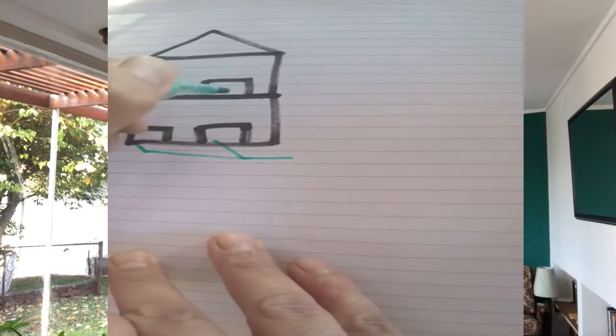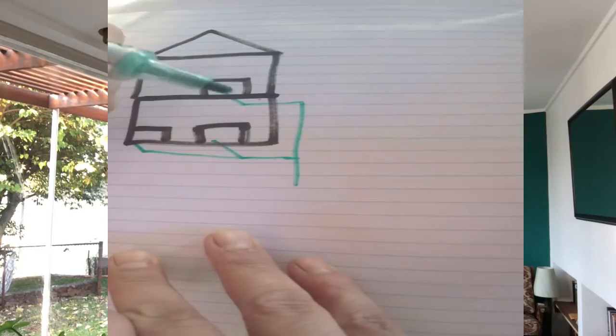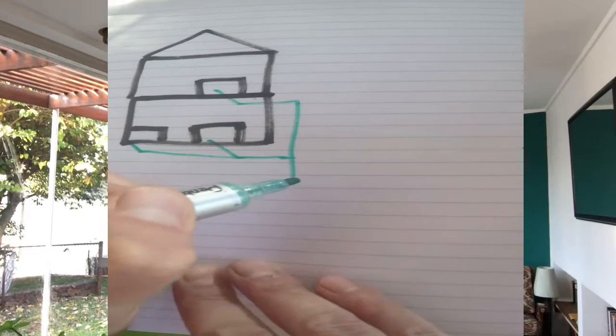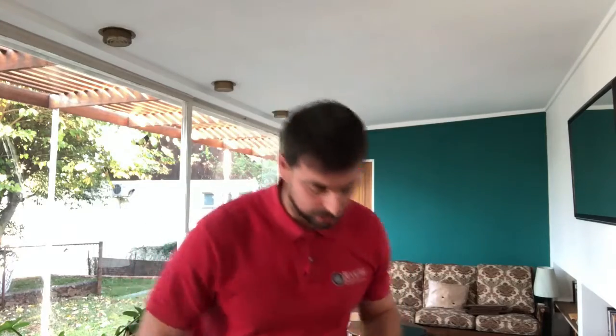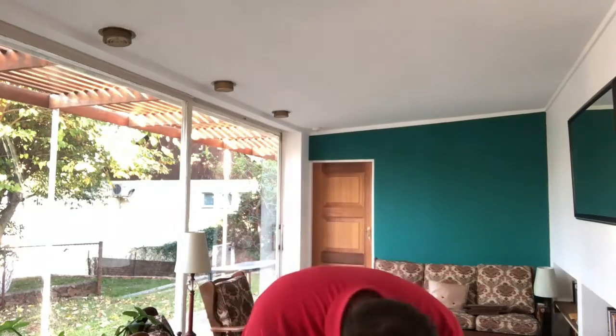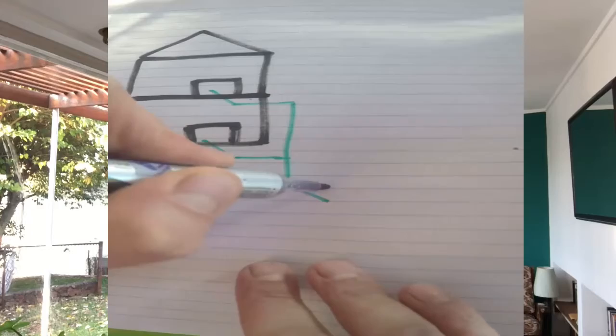Now these pipes are not connected to the toilet, because otherwise we would be dumping black water into our tank, and if we're not cleaning black water, we are going to be pumping that back into our system, and we don't want that. So these are wastewater pipes. These are the basin, the bath, the shower, and we're reusing that water. This will come out and be collected in our tank,